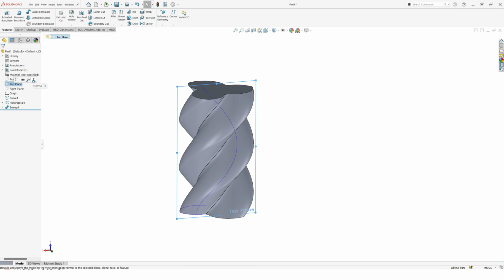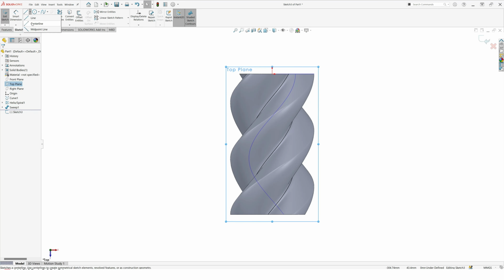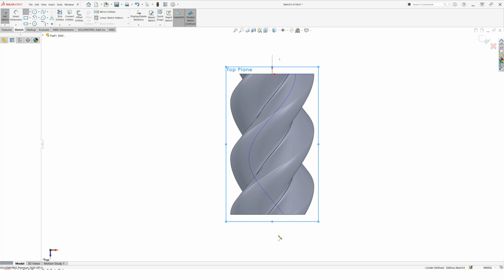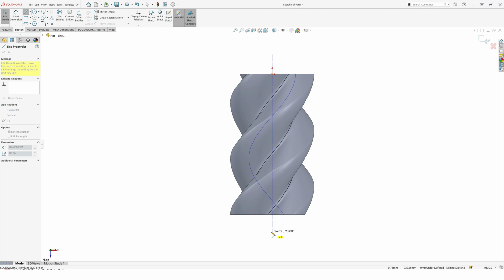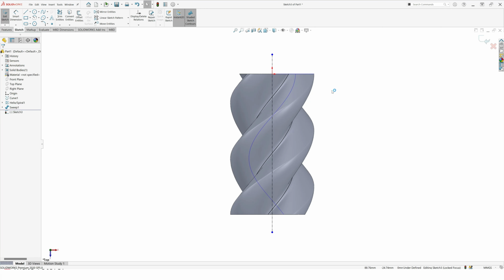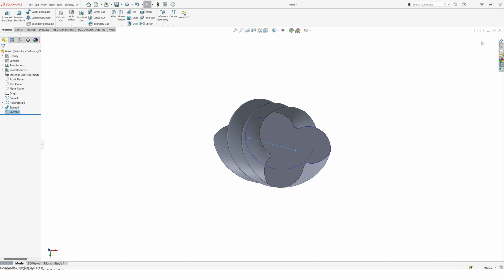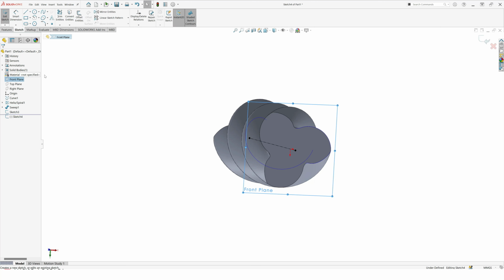And because we want to mate the main rotor with the casing, it's good to create an axis now. We make a sketch for the axis center and create this dashed line. Also, because we want to create the gear ratio between the main rotor and the gate rotor, it's good to create another pitch circle for mating the pitch circles between the main rotor and the gate rotor.